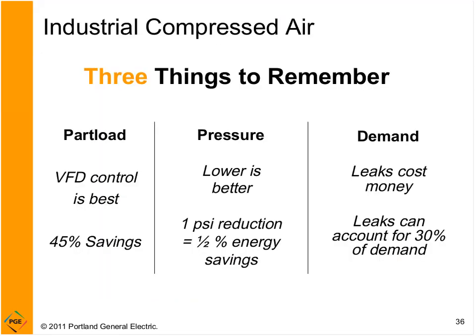So please remember, out of all this, we're wrapping this up here. 3 big things. You will have at least one part-loaded compressor, so consider a variable frequency drive. Consider operating your plant pressure as low as possible, fixing problematic areas where the air can't get to where it needs to go, increase pipe size if you need to, save energy. Lastly, if you don't remove the compressed air from the system, you won't have to replenish it. So fix your leaks.